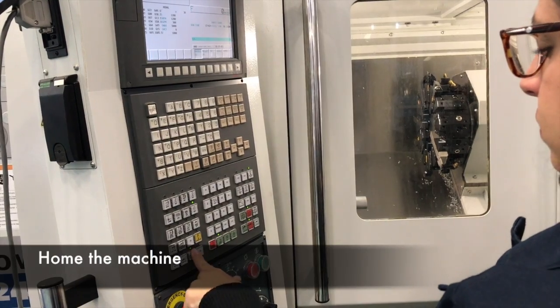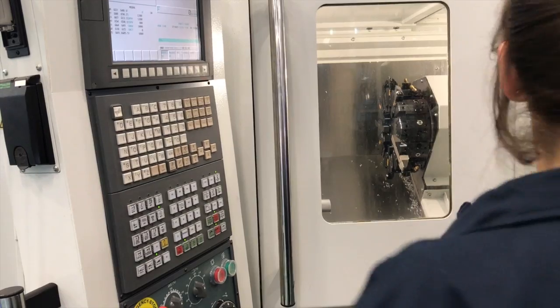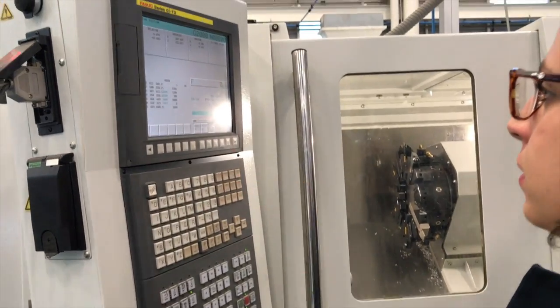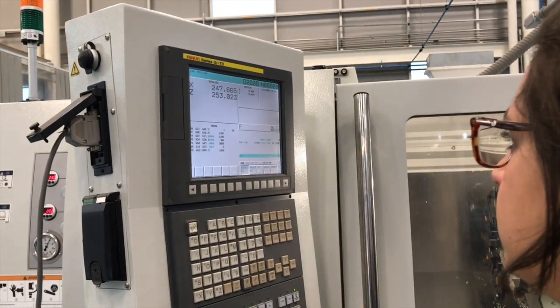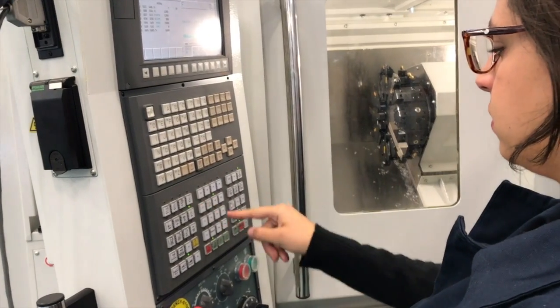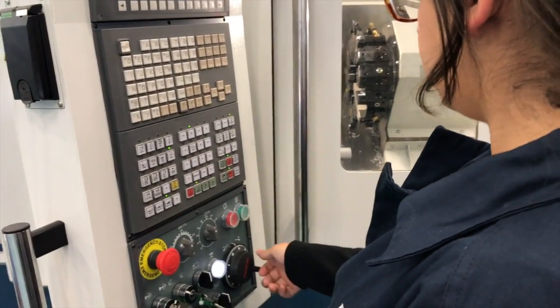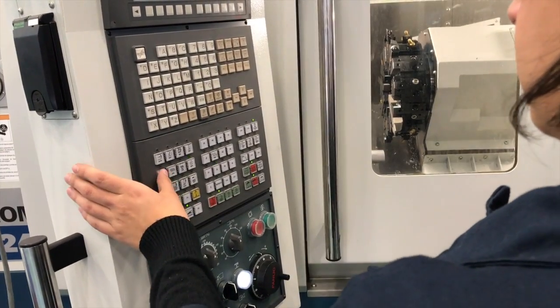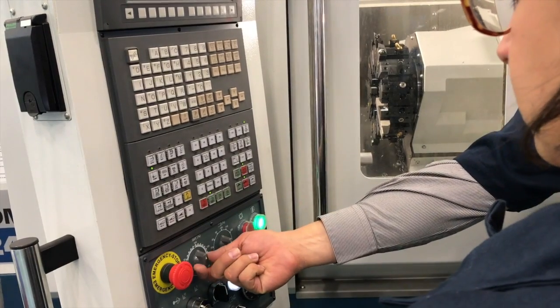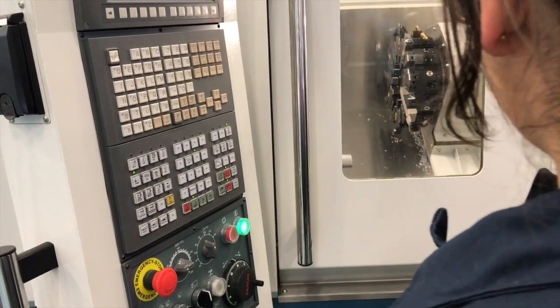To home the machine, first, we have to click the MPG button, followed by the highest incremental speed. After that, click the position button to see on the screen on which position we are in absolute coordinates. Then we have to move both axes, X and Z, only in the negative sense. After we move them both, we have to click the home position button, decrease a little bit the feed rate, and click the green button to send the turret home.